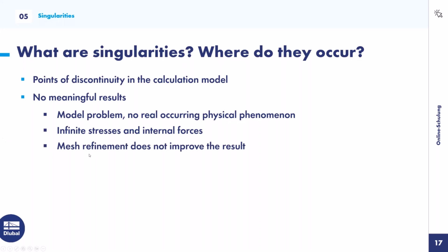Also a problem, the mesh refinement does not improve the result. It's the other way around. A mesh refinement will most likely be more harmful to the result, since the nearer you come to the point, the higher the result gets.